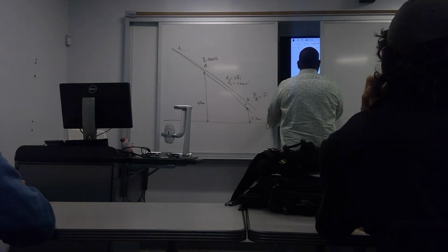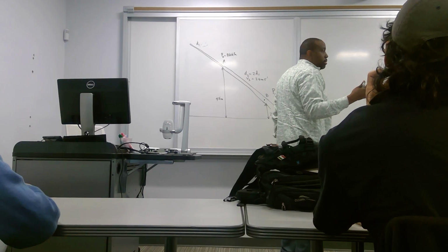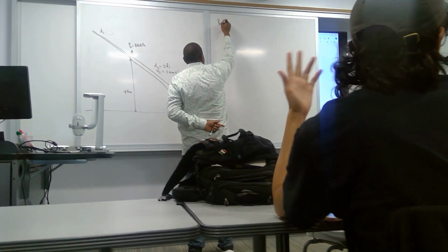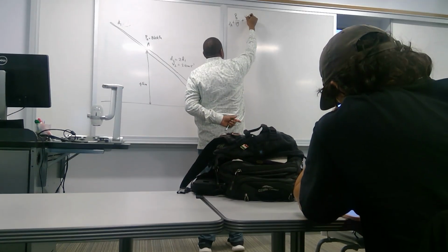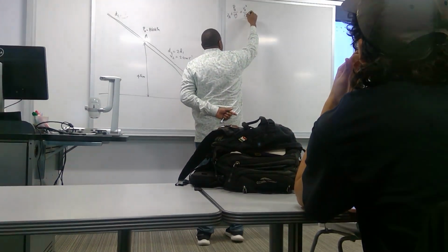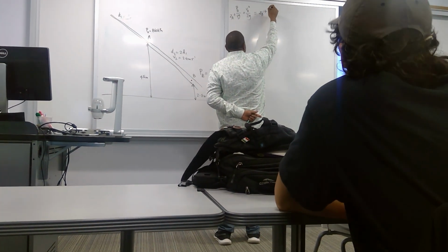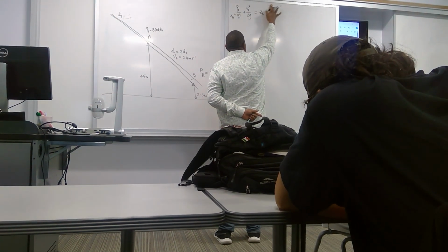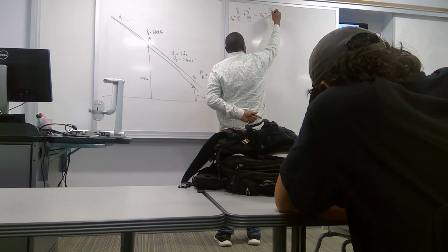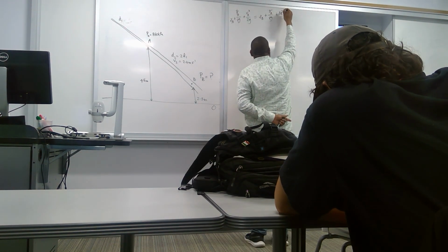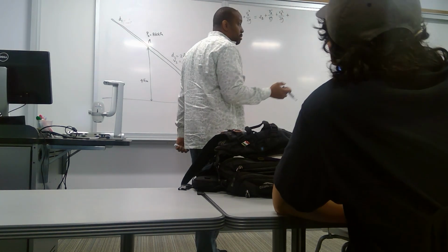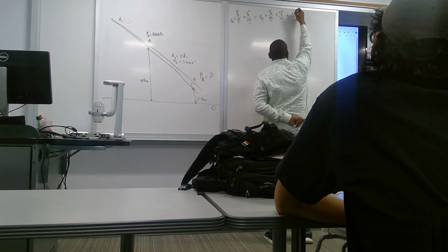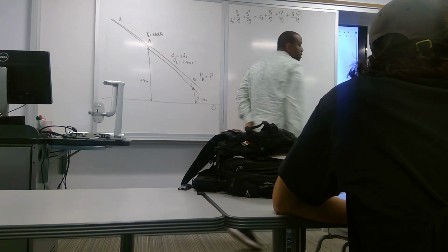It gave us that, so it doesn't matter, right? So I can say ZA plus PA on rho g plus VA squared on 2g is equal to ZB plus PB on rho g plus VB squared on 2g plus what? The shock loss, which is VA minus VB squared over 2g. That's the head loss, right?